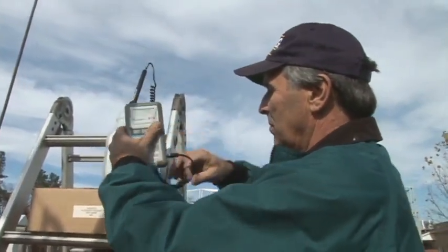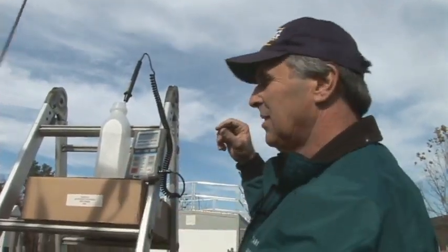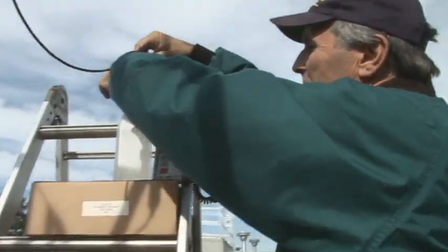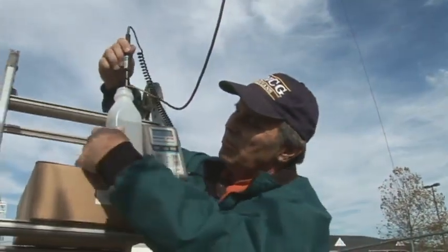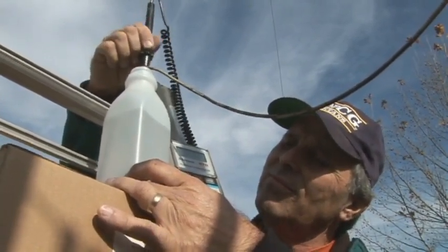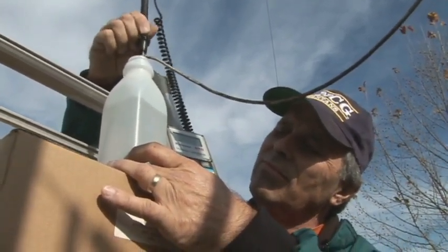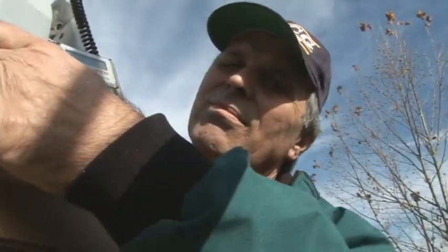This is performed by adding ambient temperature water to the water container. The outside technician has dumped out the water slurry and will now prepare for the second calibration point. With the ambient temperature water in this container, the probe and thermometer are placed in the water bath. The outside technician should stir the water to avoid pockets of different temperatures.